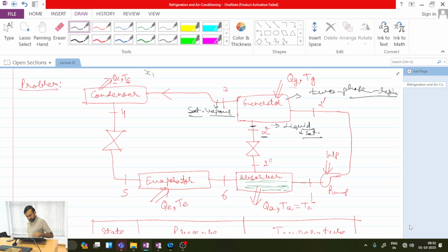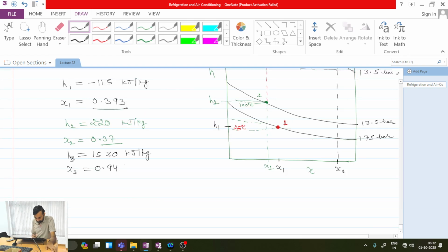From 3 to 6, I do not have anything where I can add or remove ammonia, or add or remove water. So it means that overall mixture composition at 3, 4, 5 and 6 will remain. So whatever is my X3, same will be equal to X4, X5, X6.